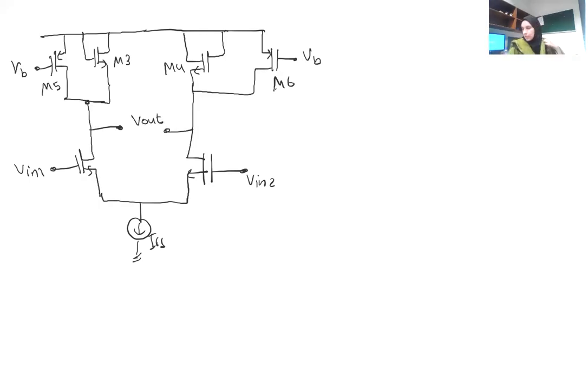Okay, so now we want to find the gain for the circuit. Lambda is greater than 0, means we need to consider the R outs. Okay, any idea? It's an exact replica across a line of symmetry that we can draw here. We can have this as a virtual ground, and we can find the gain for half of the circuit.